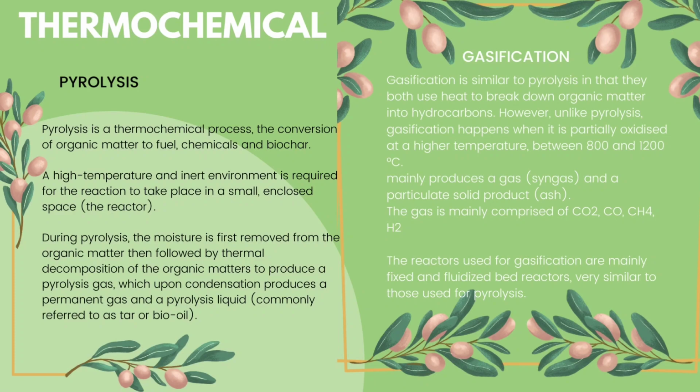During pyrolysis, the moisture is first removed from the organic matter, followed by thermal decomposition of the organic matter to produce a pyrolysis gas, which upon condensation produces a permanent gas and a pyrolysis liquid, commonly referred to as tar or bio-oil.